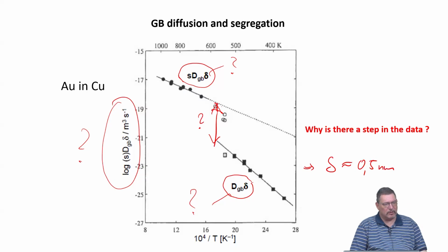0.5 nanometer has been established. So this is why we know that the grain boundary width, this transition zone in a high-angle grain boundary, is 0.5 nanometer for basically all metallic materials that have been tested so far. So a clever combination of C and B type kinetics can give you this type of description.